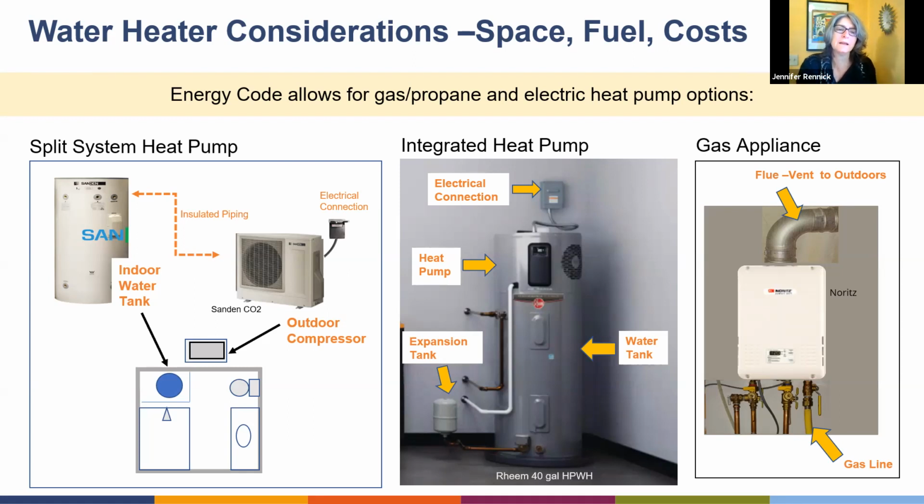And you need a couple of feet to 3 feet clear in front of it and on the left side if you're facing it, because that's where it pulls the air in. And other than that, and to keep it clean and away from dryer lint and leaves, just like you would with any outdoor compressor unit, you're set.